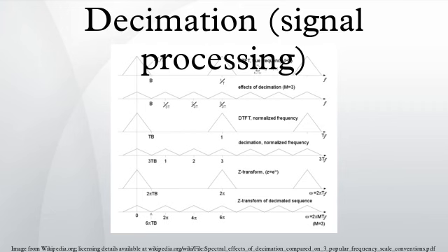Anti-aliasing filter. The requirements of the anti-aliasing filter can be deduced from any of the three pairs of graphs in Fig. 1. Note that all three pairs are identical, except for the units of the abscissa variables. The upper graph of each pair is an example of the periodic frequency distribution of a sampled function, x(t), with Fourier transform, X(f).